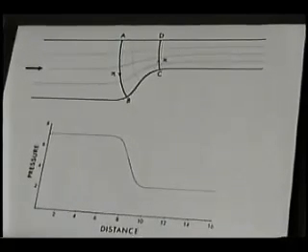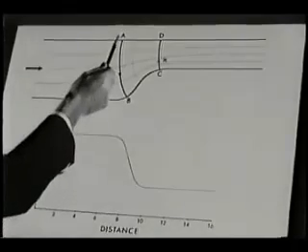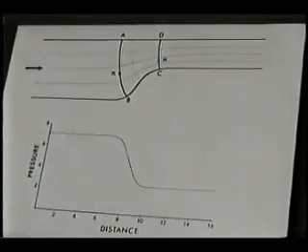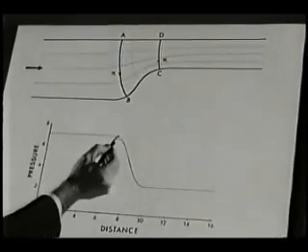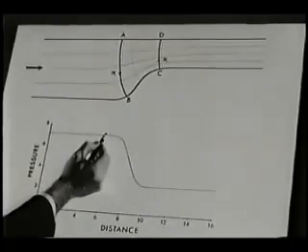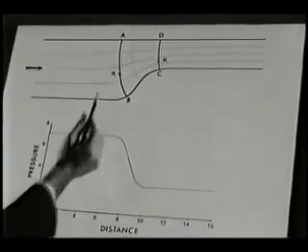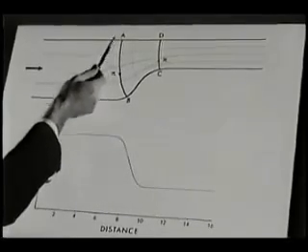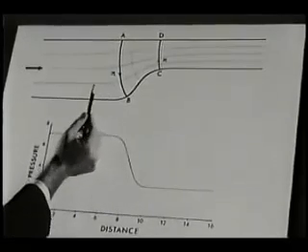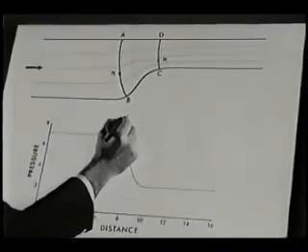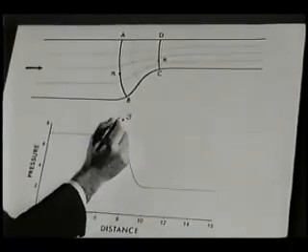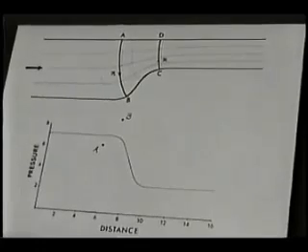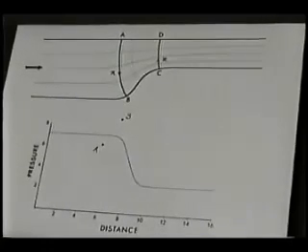But because of streamline curvature, the pressure increases from A to B, so that the pressure at B will be greater than the pressure at A. Similarly, the average pressure on CD will be only slightly greater than the downstream pressure. Again, though, because of streamline curvature, the pressure will increase from C to D.